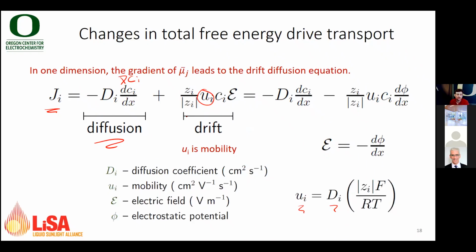So it's just diffusion plus drift, but the other thing that's really important, going back, I know Joel probably talked about this stuff, Werfel, a famous guy in the photovoltaic community, talking about how to think about photovoltaics. One of the big points, also relevant in electrochemical systems, is that it's a somewhat artificial separation into a drift and diffusion current. You can certainly write the math that way, and you can write currents like that. That's fine. But the reality is there are gradients in free energy that drive transport. And sometimes when you artificially separate things, you can get yourself confused. So make sure you come back and check that it makes sense and the free energy is doing what you think it should be doing.